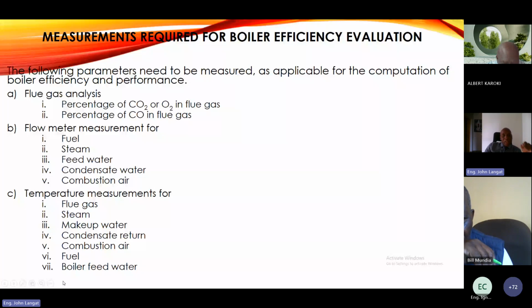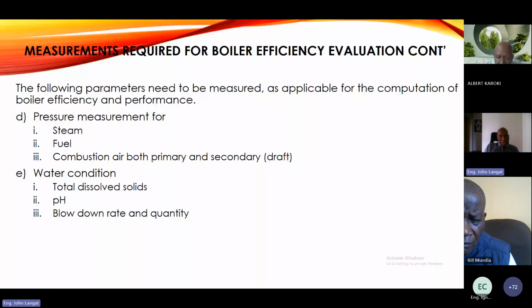You see, the feed pumps are designed not to operate as steam pumps. They are designed to operate as condensate pumps. So by the time your temperature reaches 100 and you are pumping that water into the boiler, you will kill that pump. And subsequently, you might end up killing your whole boiler. Yeah. So you are still measuring on measurements.